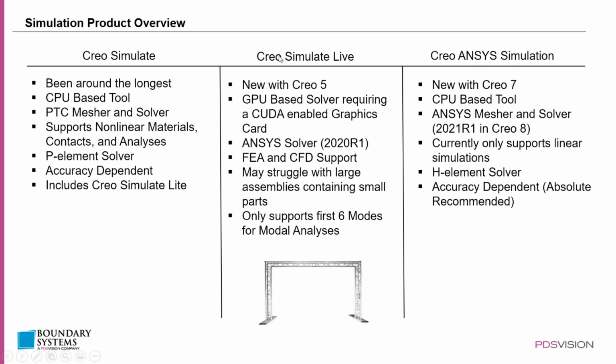I'm now going to move on to Creo Simulate Live. This was developed and added with Creo 5. So that was about between 3 and 4 years ago. And rather than being a CPU-based tool, it is a GPU-based tool. I'd like to mention that right off the bat because it does have very specific hardware requirements to be run. In order to run this, you do have to have an NVIDIA CUDA-enabled graphics card.